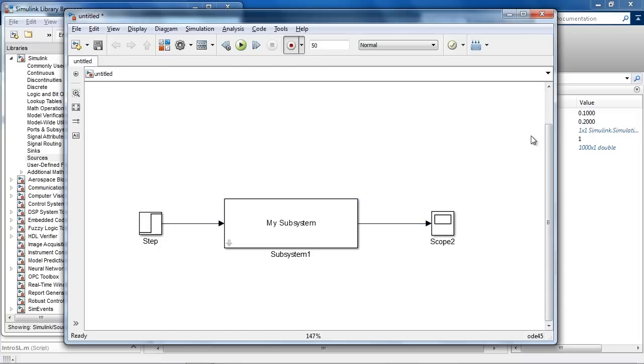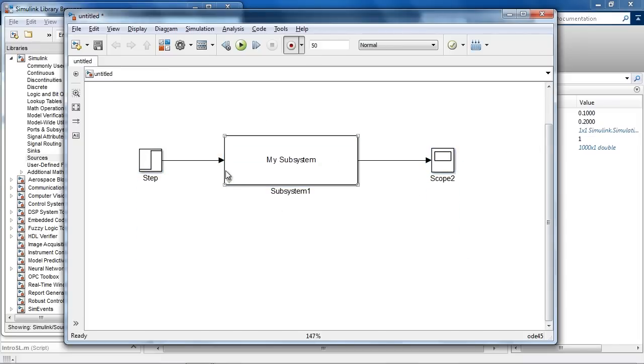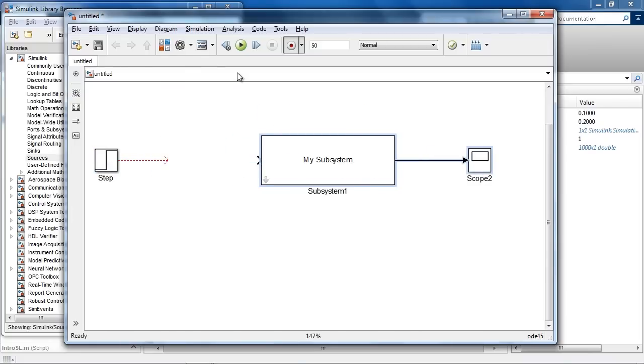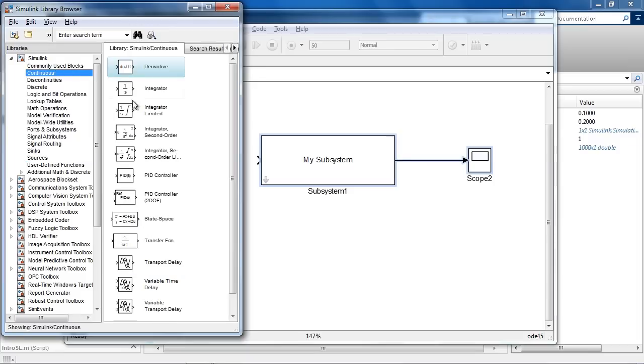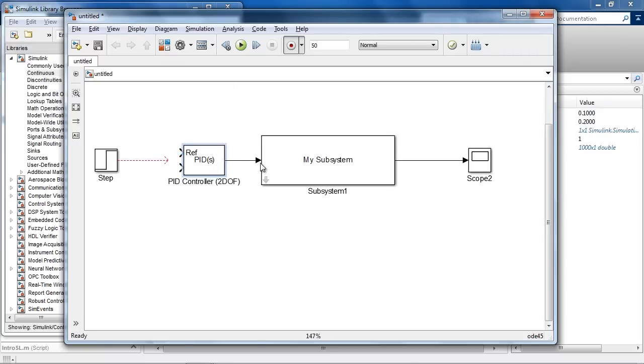All right, so the next thing I want to do is actually create a feedback controller for this. And typically if you've done controls in the past, that might take a little while, but with Simulink I could do that in about 2 minutes. Oh yeah? Yeah. Excellent. Let me drag in my PID controller block. And I'll connect my reference signal. Yeah. And I'll feed back.